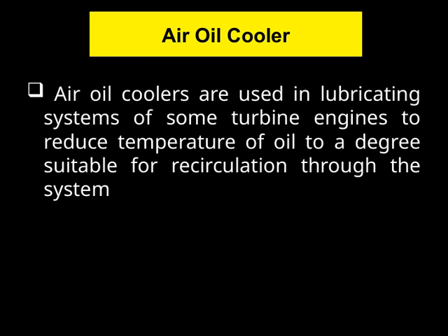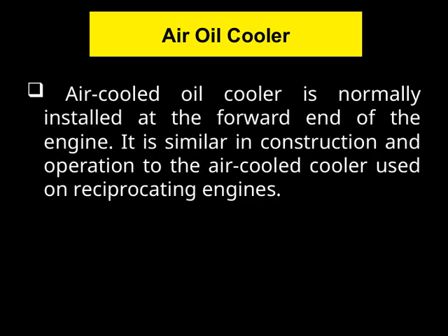This cooling process is essential for ensuring the engine runs smoothly and reliably. Overall, air oil coolers are a key component in managing engine temperature and protecting engine components from heat-related damage. Now, let's talk about the air-cooled oil cooler, which is typically installed at the forward end of the engine. This placement is strategic because it allows the cooler to effectively dissipate heat by utilizing the incoming airflow.